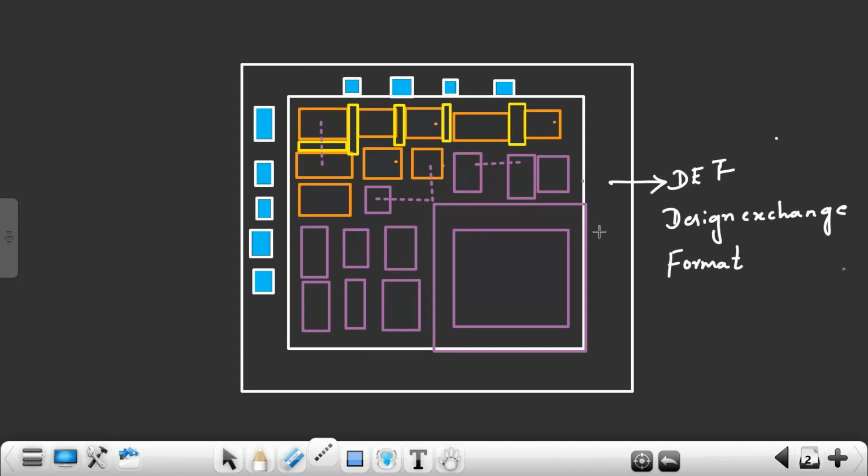They would have already considered that extra area. Without extra area, you should not do the physical design, or else you cannot complete. You will end up with overutilization and many shorts. Will that be considered in the synth stage also? Yes, it has to be considered. The extra area is already present in this floor plan DEF.